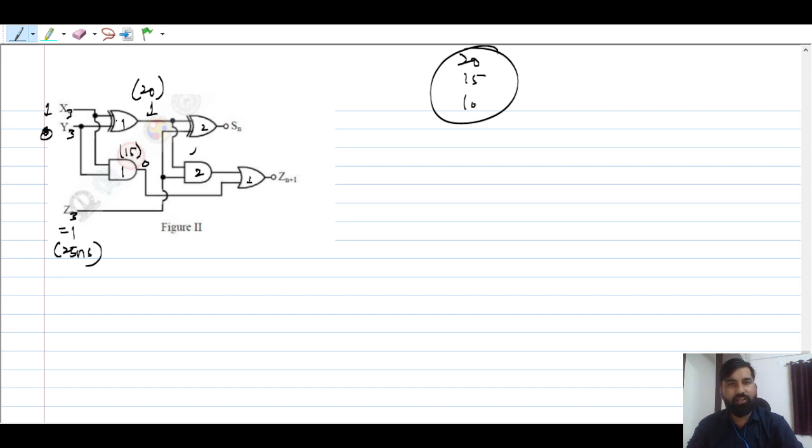This Z3 is not going to affect the first XOR, but Z3 is going to affect the second XOR. This one will be available at 25 nanoseconds, but this one is available at 20 nanoseconds. So this XOR gate has to wait till 25 nanoseconds, then it will respond after 20 more nanoseconds. This is S3. S3 is going to be 0 or stable after 45 nanoseconds, right? So we always consider the maximum delay; the gate has to wait up to that, okay, to respond.